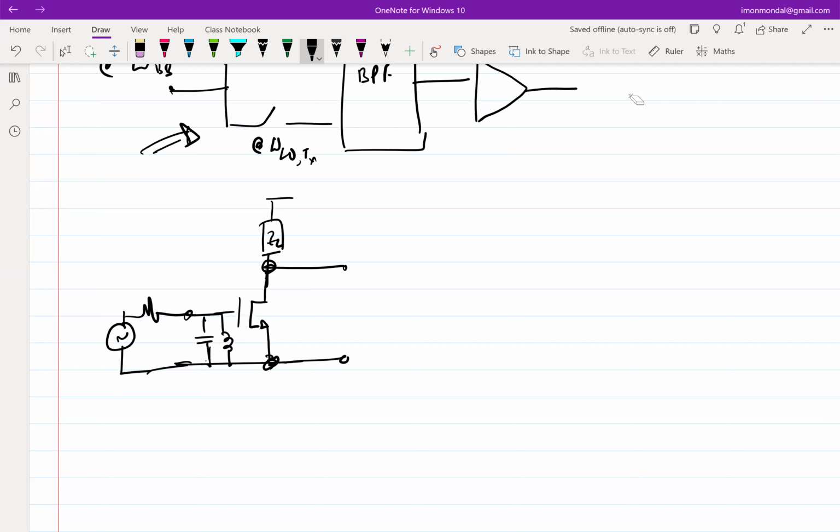We need to have some current gain. That is correct, I agree. But the transit frequency comes because you have a capacitance and there is a voltage drop, and the corresponding gm times VGS also drops. But if I tune out the capacitance, then that should not be an issue, right? Then...